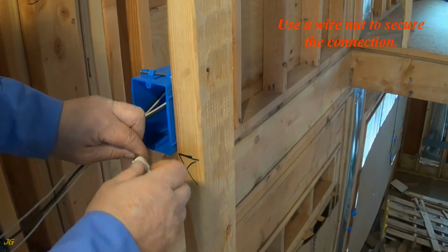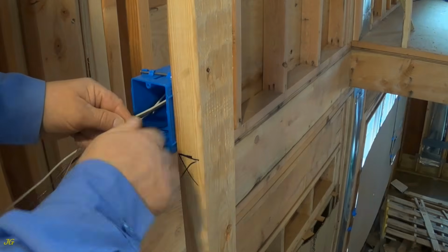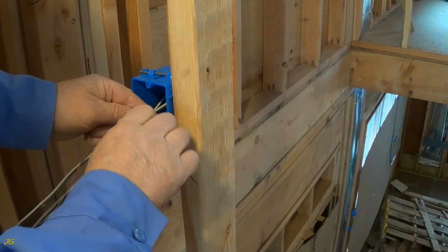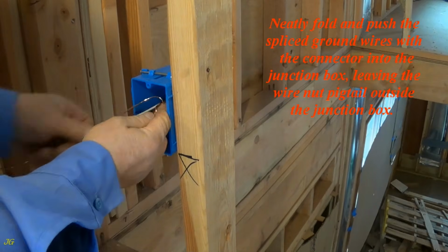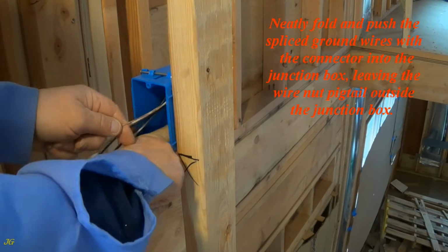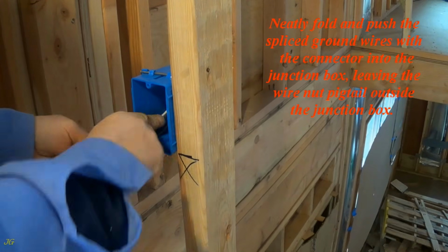Use a wire nut to secure the connection. Neatly fold and push the spliced ground wires with the connector into the junction box, leaving the wire nut pigtail outside the junction box.